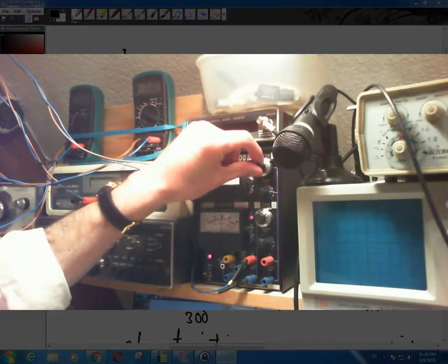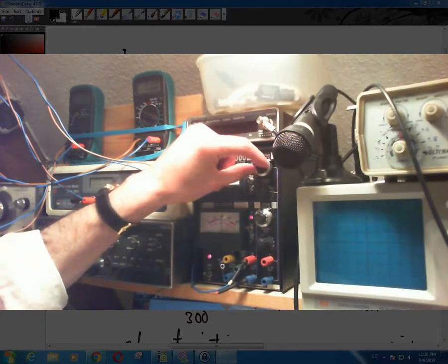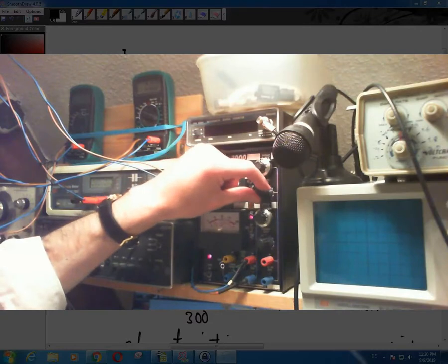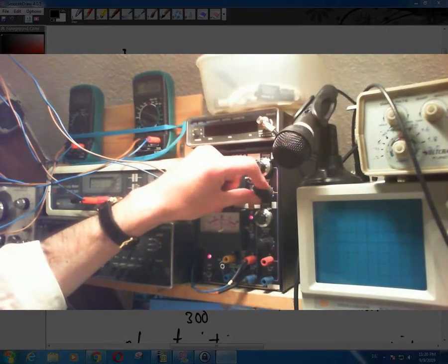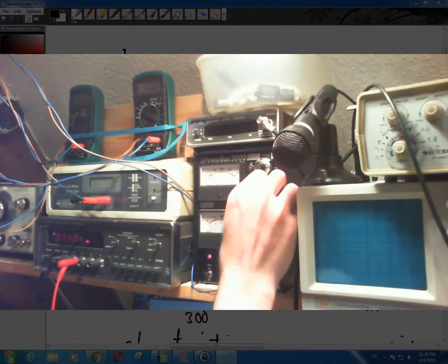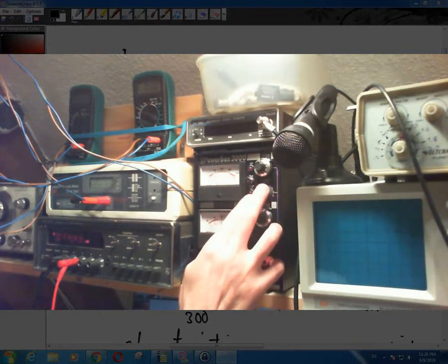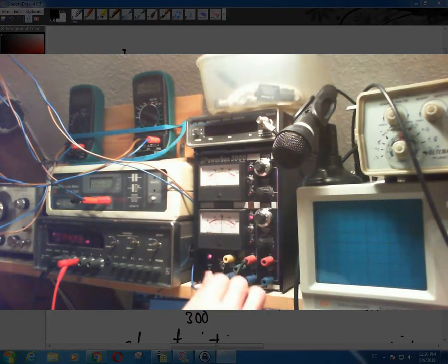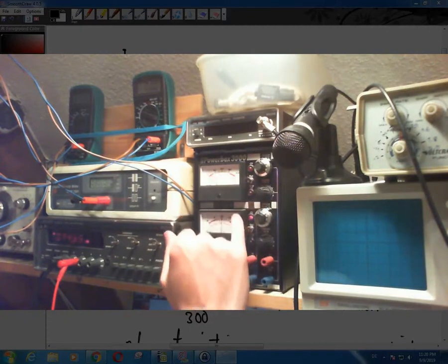On these 2 rails you can change the voltage. You can keep changing the voltage using these potentiometers, and you can also limit your current using this knob. Using this potentiometer, you can limit your current, meaning that you can set your current, for example, to 100 milliamps. If you set your current to 100 milliamps, then your current will not exceed 100 milliamps.